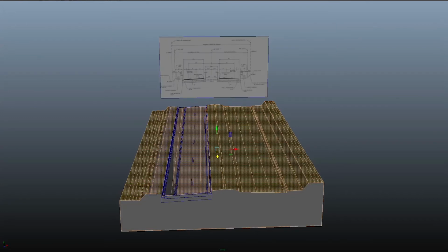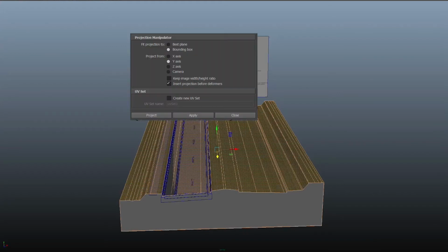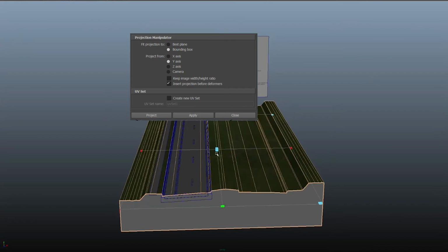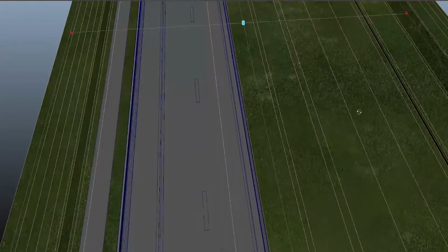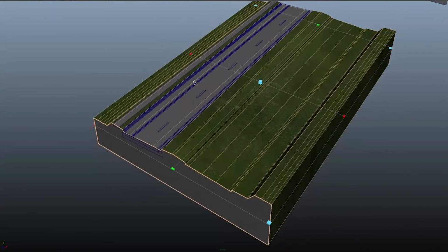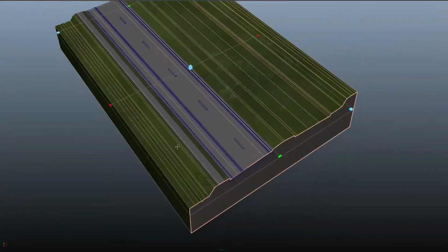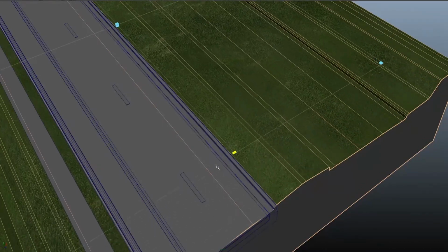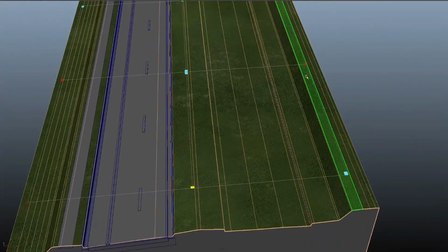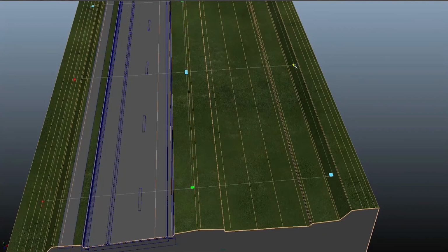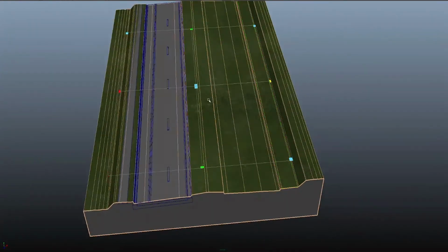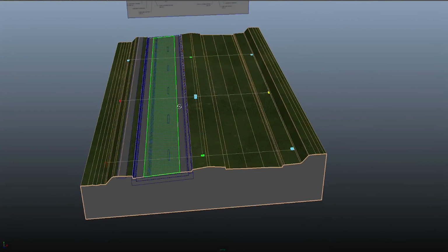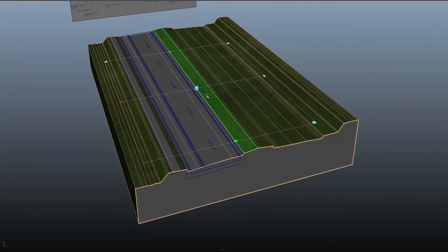Just slap these textures flat, straight down on these models. Make it simple and easy and quick. So project, and then as you can see here, now we have a nice little ground texture. And if you want to repeat more, if you want it to look like there's a little more density, you can do this, but be careful not to repeat too often, otherwise it's going to look like it's tiled. It's going to look like a checkerboard, and try to make these things as seamless as possible because it adds a lot more realism and believability and appeal to the renderings.